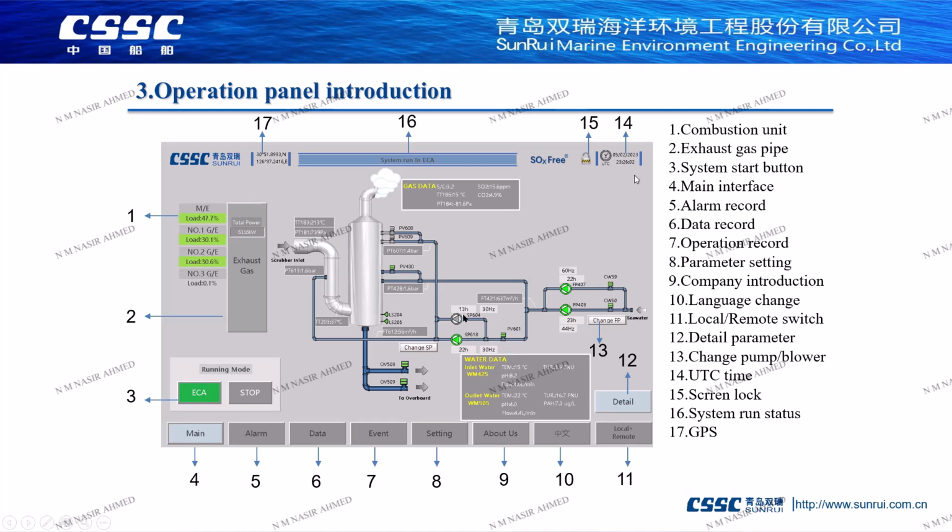The main purpose of the pre-spray pump is to spray seawater to the secondary tower, and at the same time to cool the intake gas of the secondary tower. For the main spray and pre-spray lines, we have installed flow meters to monitor the flow rate. There is also a side stream at the exit of the pre-spray pump. It goes to the top of the desulfurization tower.